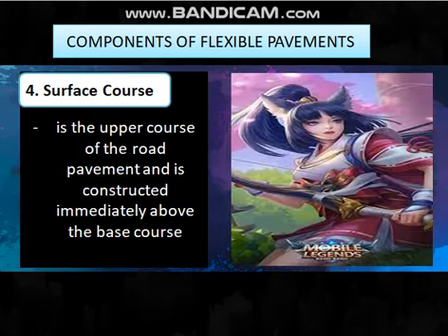So next is surface course. It is the upper course of the road pavement and is constructed immediately above the base course. The surface course in flexible pavement, guys, usually consists of a mixture of mineral aggregates and asphalt. It should be capable of withstanding high tire pressures, resisting abrasive forces due to traffic, providing a skid-resistant driving surface, and preventing the penetration of surface water into the underlying layers.